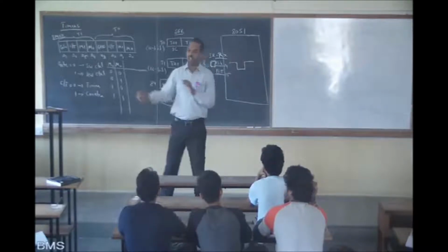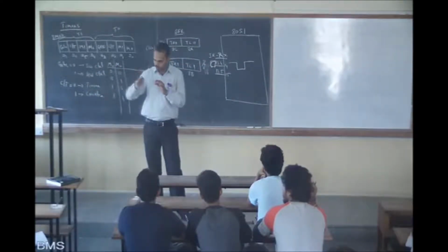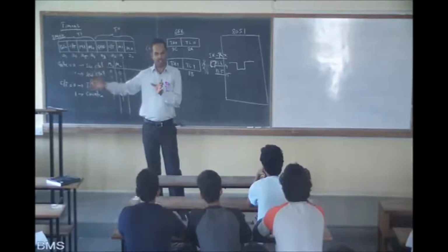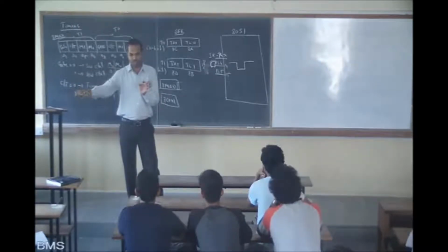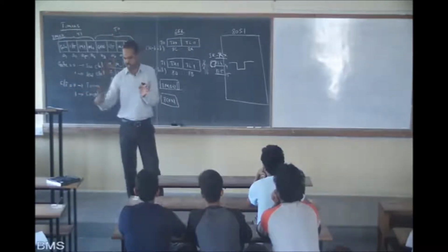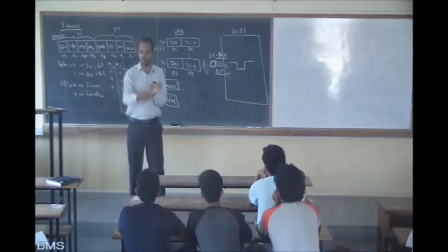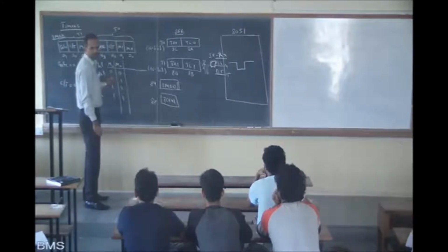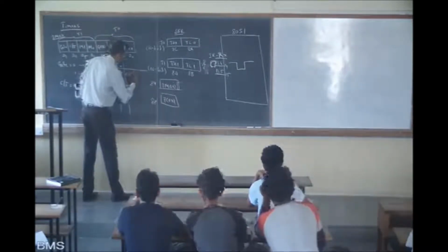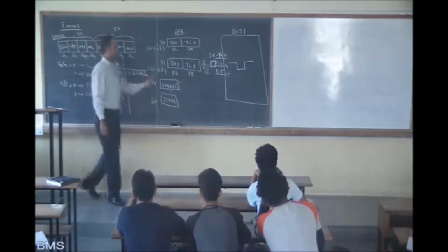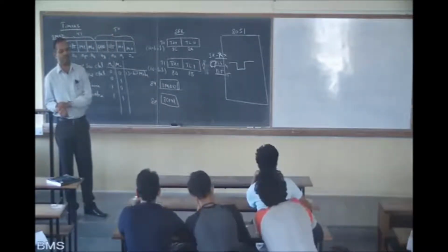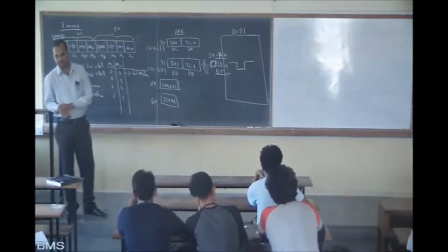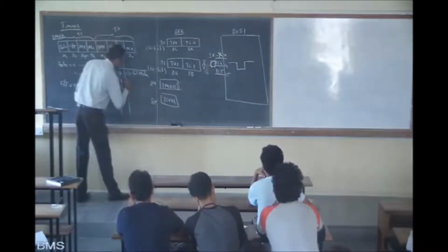These, 8031 and 8048, are predecessors, designed before 8051 and already in the market. To give compatibility between them and 8051, they have given one mode which is called the 13-bit mode, that is mode 0. Though it is a 16-bit register, it acts like a 13-bit register and does the counting for 13 bits only. Clear? Next one. Mode 1 is a 16-bit register.